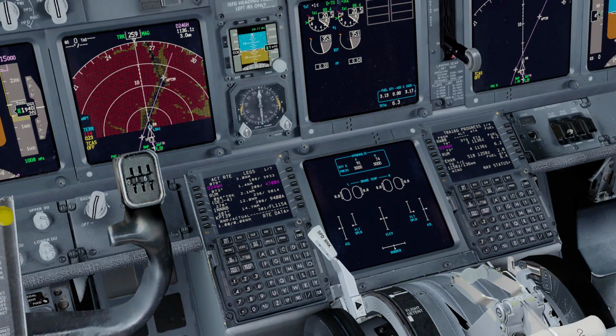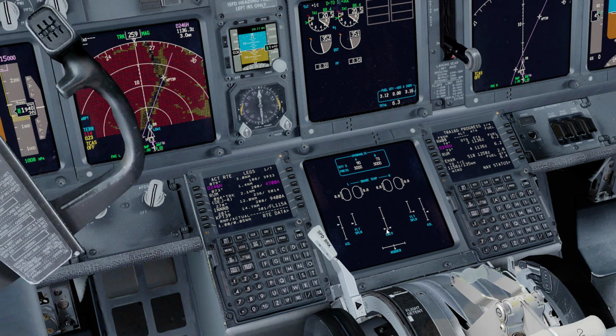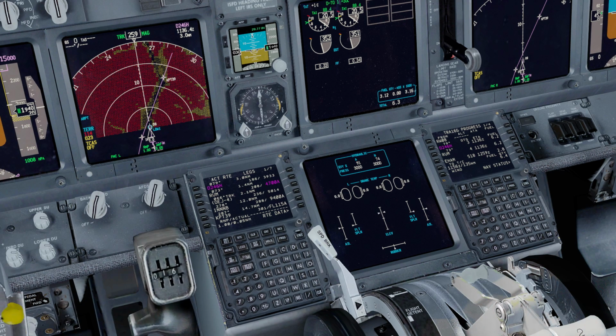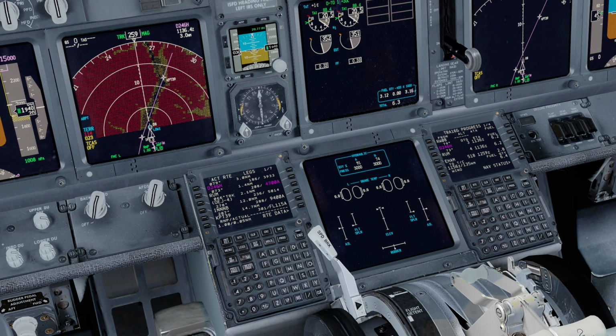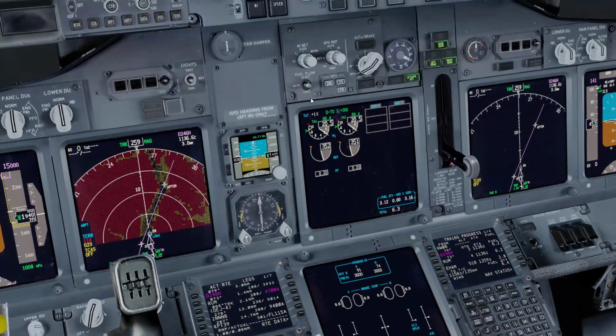Okay. Now this is what I've seen from a cockpit video. I'm sure it's kind of different for every airline, but you just want to push the yoke forward, make sure that you have elevator deflection right here, and check the ailerons, left and right, and then pull the yoke back to check the upward movement of the elevator. That's also all been checked, and now we can check the rudder, left, center, and right and center. Okay, so the flight controls have now been checked.